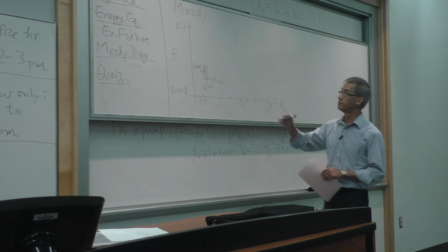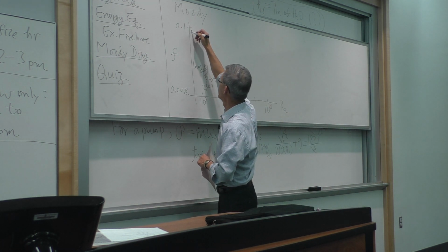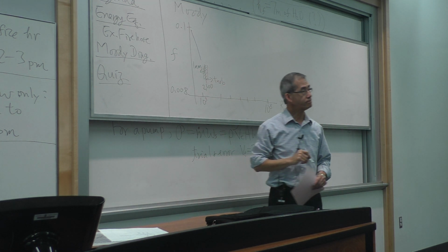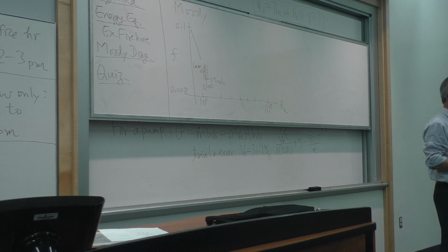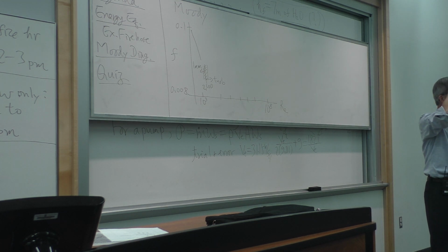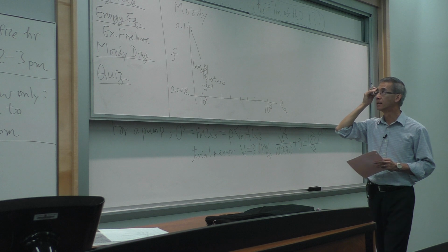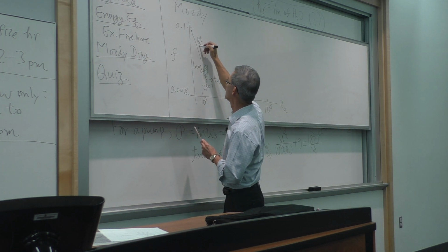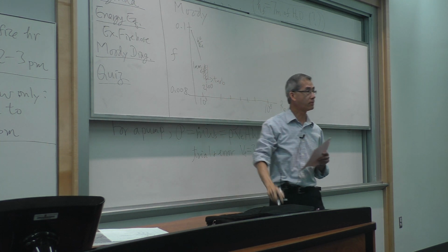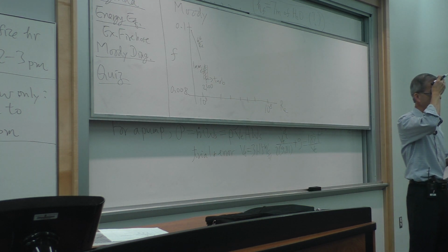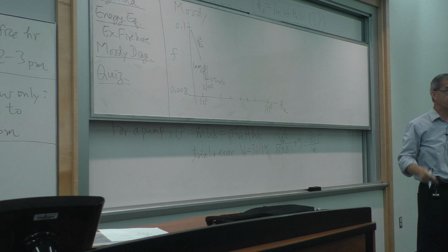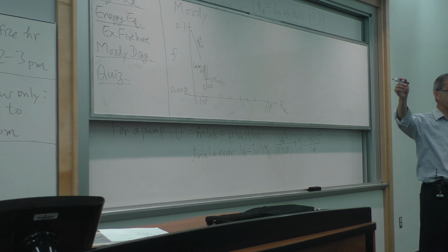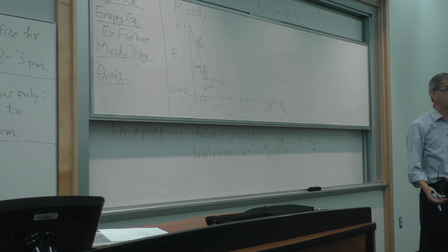The curve here is a straight line. And that actually is an in-class problem, which I will talk about momentarily. That straight line is a slope of 64 over Reynolds number. And we're going to show how that comes about. That's your in-class problem. Right? Does that ring a bell? Have you seen this? Why do I have to tell you there's a cast iron pipe as opposed to polished aluminum pipe or glass pipe?